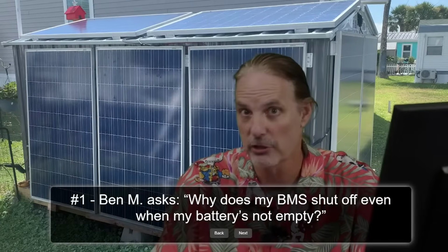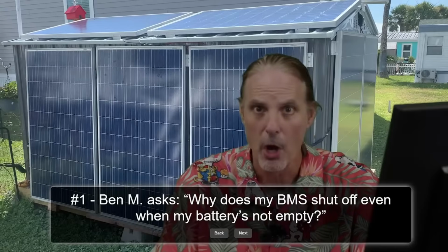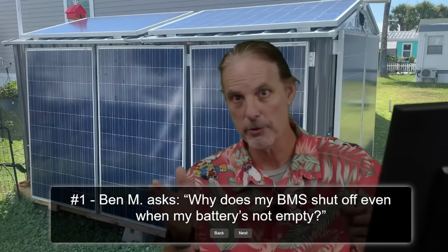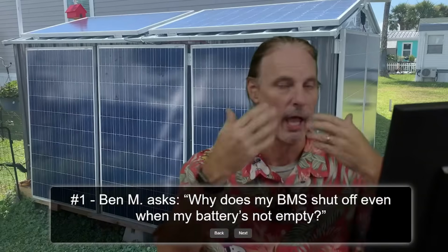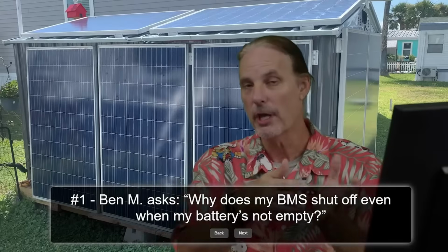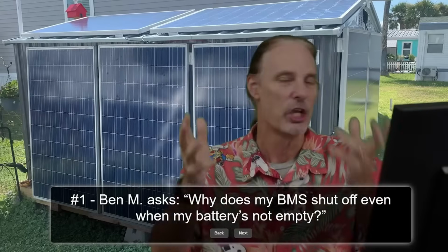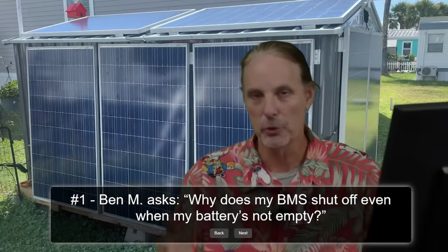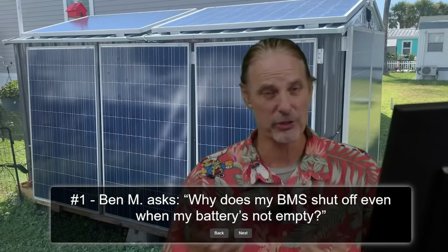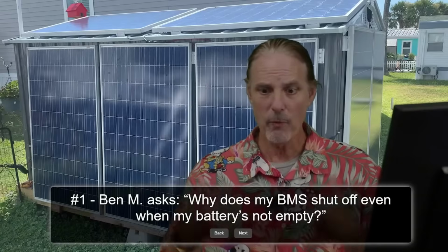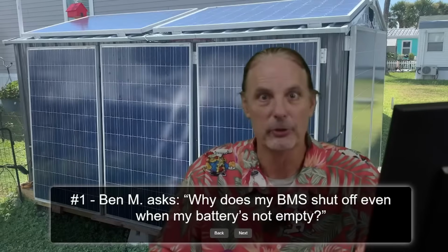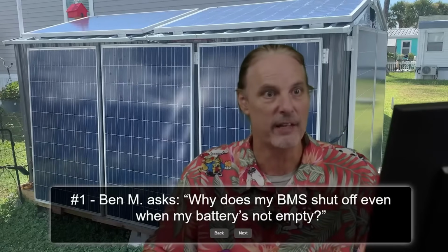And let's talk about the 6000 XP from EG4 is one of those, where if you're running closed loop, meaning that the inverter is communicating with your battery, and your battery is telling the inverter how much power it can take, how many batteries are connected, how much space it has. It also starts around 10% saying, you're not allowed to get any less than this. We're going to switch you over to grid power and stuff like that, which is not ideal for someone like me who's off grid. I want my battery to run until it absolutely is dead, if that's the case.